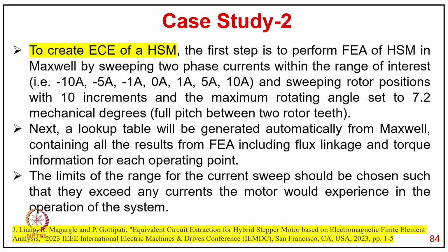To create the EC of SCM, the first step is to perform finite element analysis of the hybrid stepper motor in Maxwell by sweeping the two-phase current over the range of interest, that is -10, -5, -1, 0, 1, 5 and 10, and sweeping the rotor position with 1 degree increment and a maximum rotating angle set to 7.2 mechanical degrees, the full pitch between the two rotor teeth.